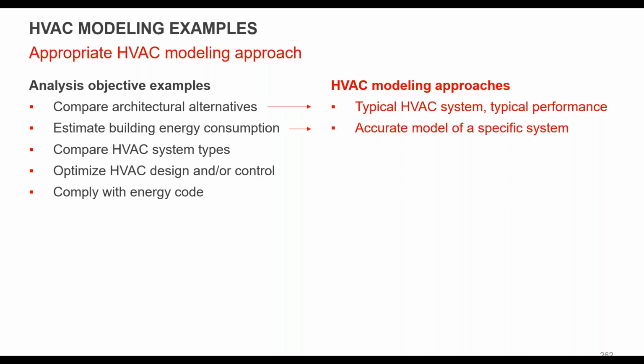If you're looking at a true estimate of building energy consumption, then yeah, you're probably going to get into the details on the envelope, the lighting, the HVAC, everything else that would affect total building energy consumption. So that might be a much more detailed level of model. For comparing HVAC system types, you want to put enough detail in that you can actually make a reasonable judgment on whether one system is better than the other based on the results of the model.